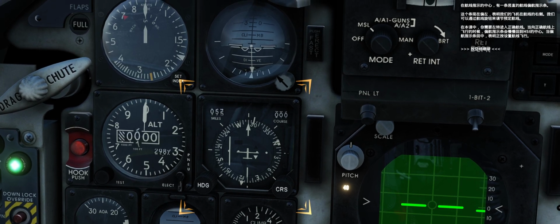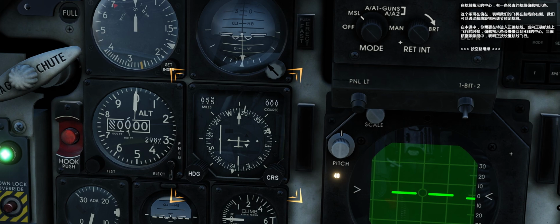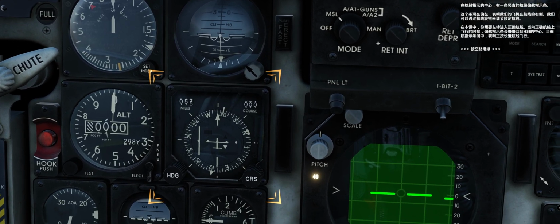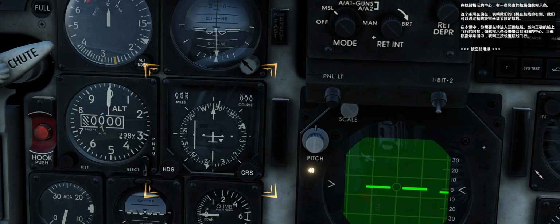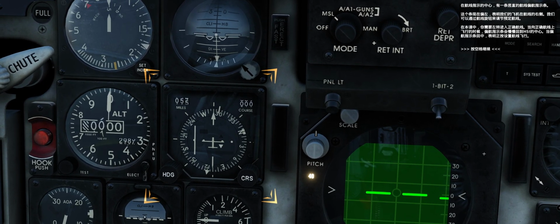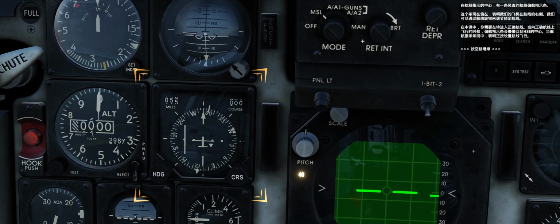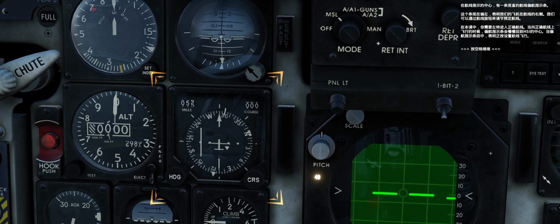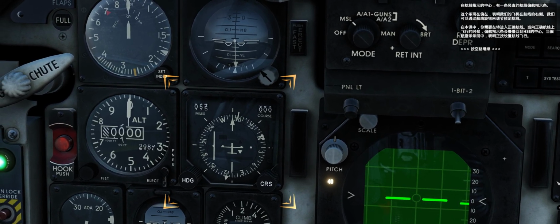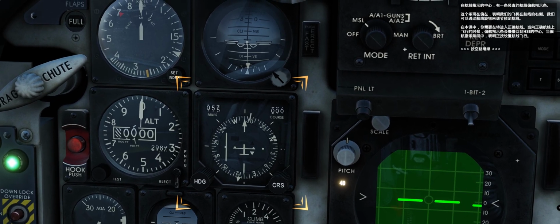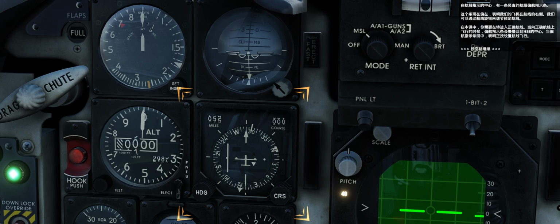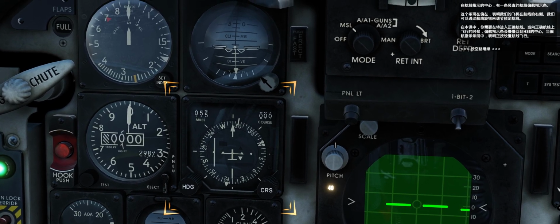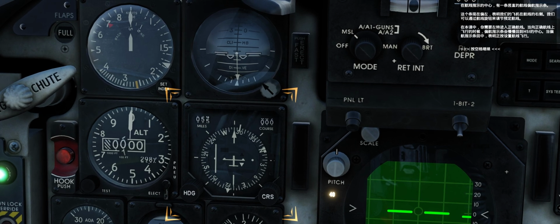In the center part of the course pointer, which should point to the takeoff course, there is a vertical bar that indicates the level of course deviation. This bar is deflected to the left, indicating that our aircraft is located to the right of the course line. This can be adjusted using the CRS knob and passing over the TACAN station. In this case, you will need to come left to get on course. While flying towards the desired course, the deviation bar will move towards the center of the course line in the HSI. When the deviation bar is centered, fly along the course as set by the CRS knob. Press space to continue.